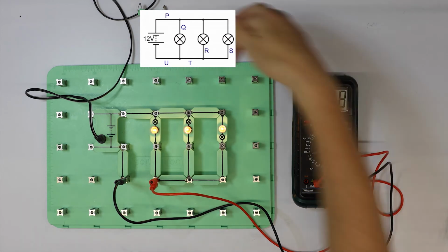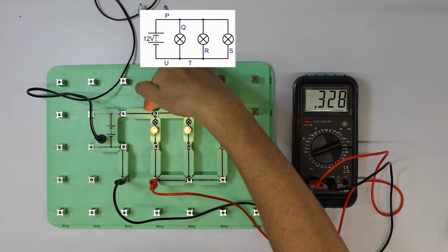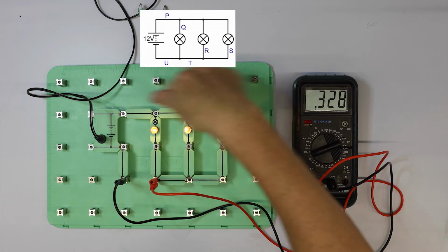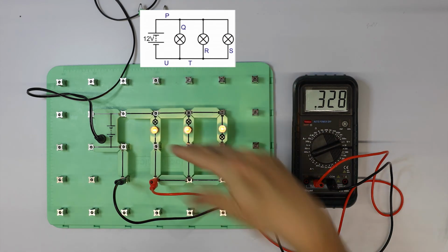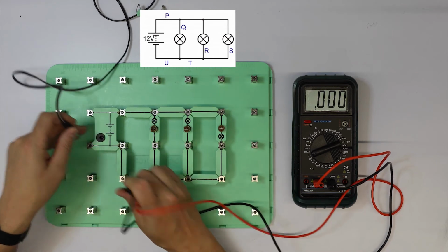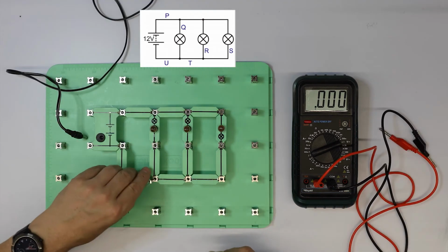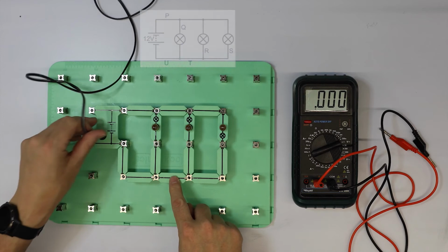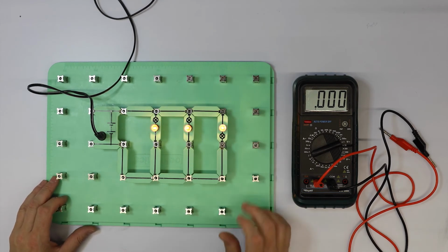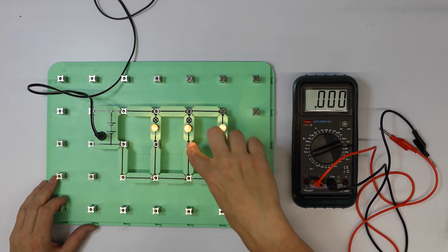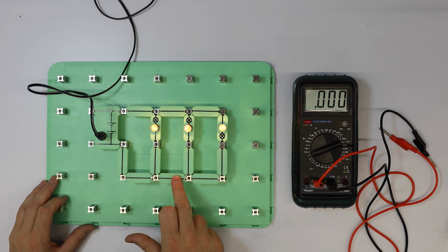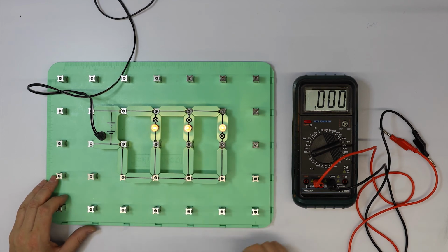So we've seen that when we divide the supply into 3 similar parallel branches, then the current is split 3 ways. We also saw that when we measured the current at this point here, it was double the value that was going down each one of these branches, which probably tells us that as these 2 branches come back together here, then the current that flows from this point is equal to those 2 added together.